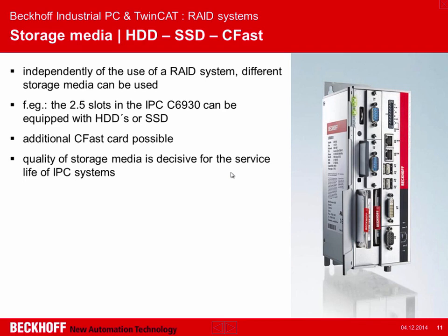Now, a lot of people believe that if you use a flash media, like a solid-state disk, you do not need to take care about any other kind of data storage because the system is so reliable. Well, this is true in case you choose the right flash media. Flash media are not equal, and the price differences of flash media on the market are normally due to very tremendous technical differences. Usually in the flash market we differentiate between so-called single-level cell flash and multi-level cell flash. And these 2 principles to store data have a significant influence on the reliability of the device.